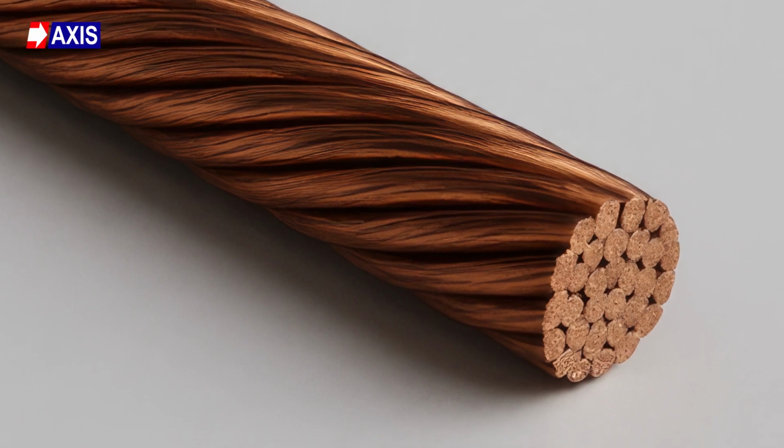Next, the different applications of shrink ratios. Various applications demand different shrink ratios. Let's understand these applications of the standard ratios, starting with 2:1. This is the most commonly used, and it works well for uniform wires, terminals, and small components. If you're insulating standard joints in control panels or organizing cables in a harness, 2:1 gives a clean and reliable finish. But not all connections are standard.